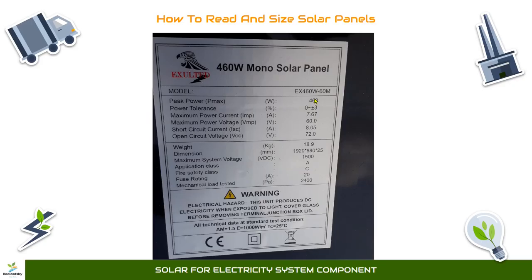If you don't put this into consideration, at peak performance this panel can surge, when you add the 3%, up to 510 or something. If that happens, you will exceed the maximum wattage of the device you are working with. So that's why you need to put all these things into consideration, and know how to use or configure your system going by the data they give you here.